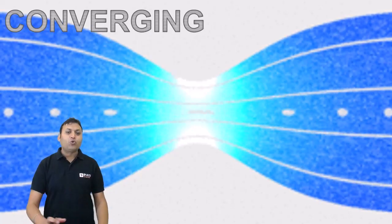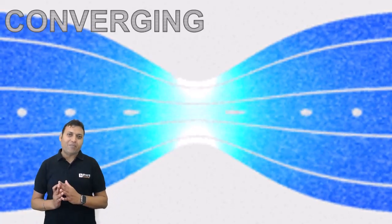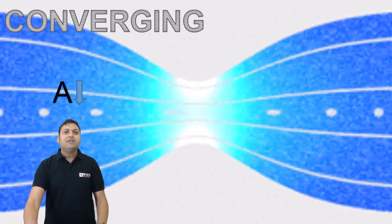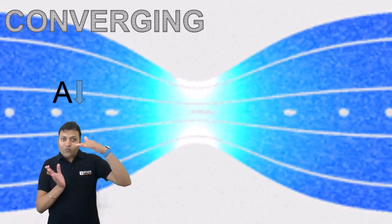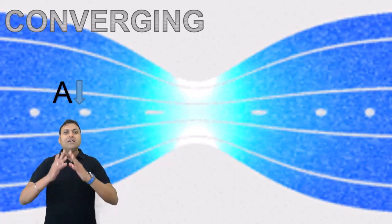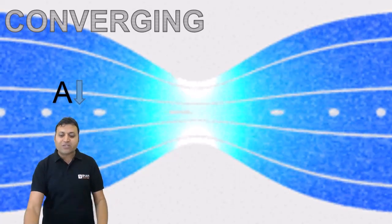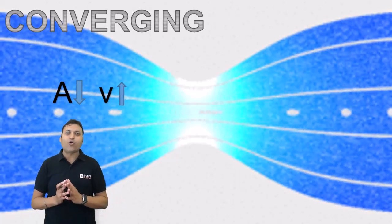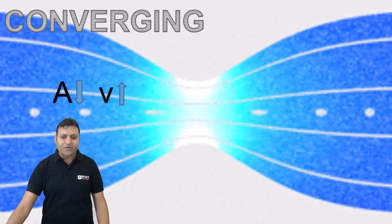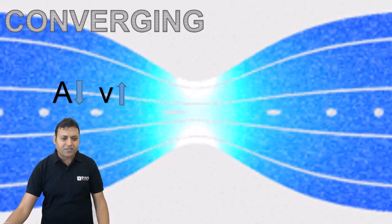If the fluid is moving through a converging section of the pipe, what will happen? The area of the flow will reduce, and due to the reduction in area of the flow, the kinetic energy or the velocity of the fluid will increase according to mass conservation. According to the continuity equation, that is mass conservation.